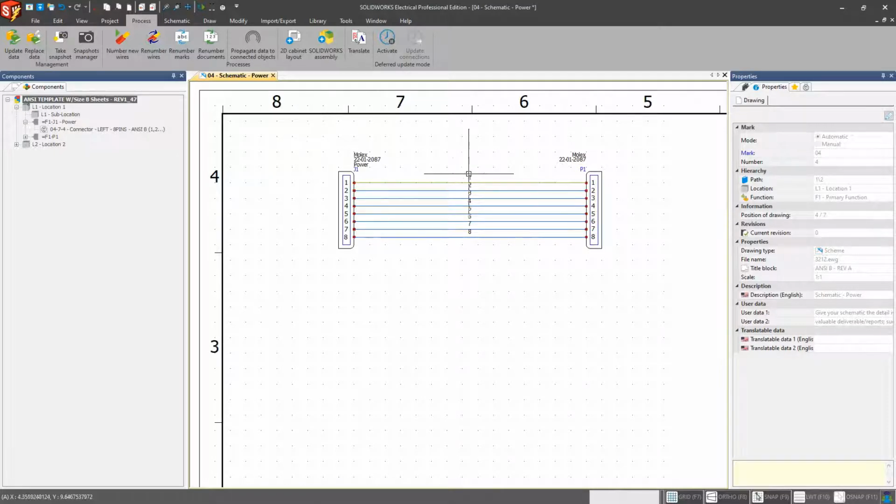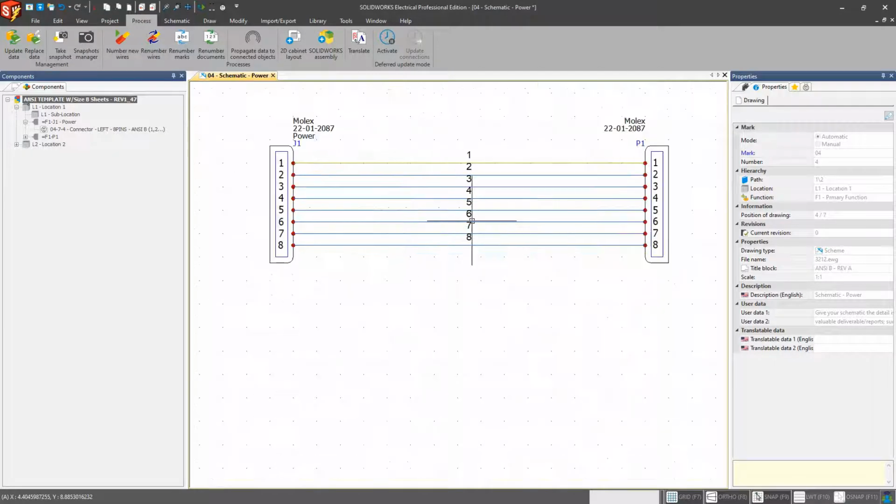In this case here, obviously it's very generic, but again, as I mentioned in the previous video about wire styles and the formulas in there, you can be as unique as you need to be for these wire styles. If I absolutely wanted to, I can change the wire numbering convention based off of the sheet and the row or the column of where that falls on the page as necessary.